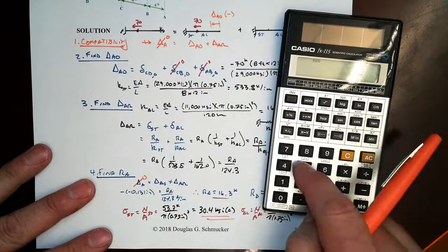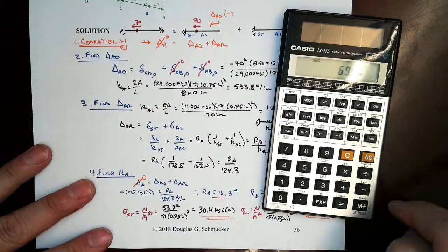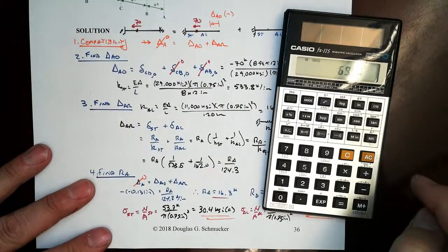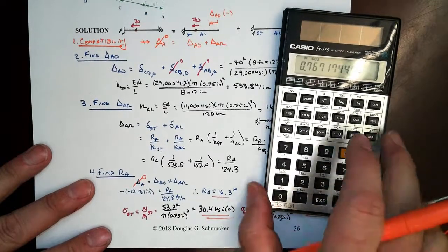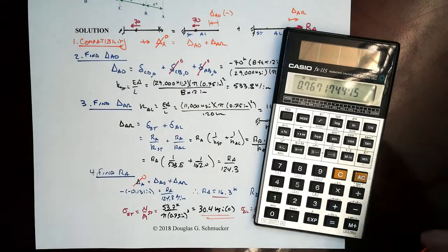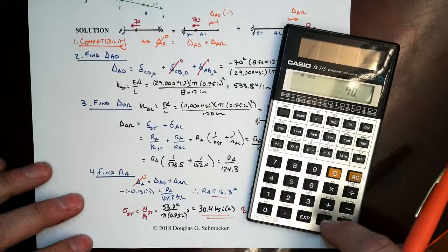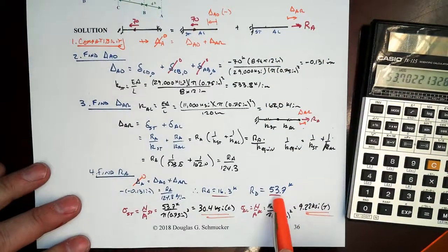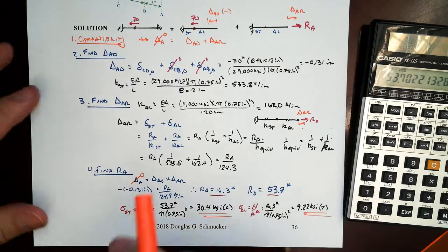If we were to add up all that, 533.8 plus 162.0, we get total of 695.8. And if we take the 533.8 and divide it by that, you get 0.767, right? So 76.7% of the stiffness is over in the steel segment. Take that times 70, and you get 53.7. Bam! Right? This is where we come up with this idea that in indeterminate systems, the load effects or the stress effects are proportioned by relative stiffness.